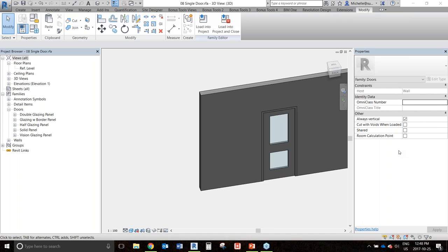For example, you have more control with your subcategories for Revit versus bringing in line work and CAD stuff. And you have the ability to add materiality to extrusions in Revit, versus if you just bring in a 3D entity, you don't really have control over picking specific parts of them and being able to turn them on or off in certain views. So in general, I prefer to have real Revit geometry, unless there's some instance where it would just be really difficult to do so. But I would say 98% of the time, that's what I'm doing.